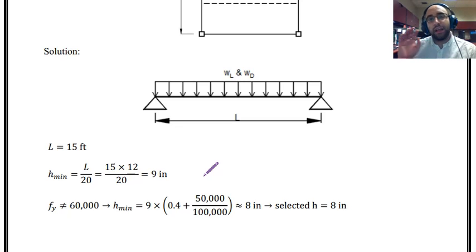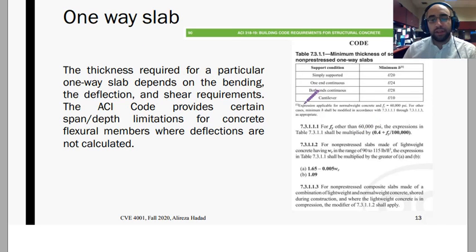Once you design this and you design the slab in the project, you will become more and more familiar with the slab design, and then based on that you can see that we are not really worried about the design of slabs, because just providing the minimum height and the minimum reinforcement will give us enough strength to carry regular loads. So minimum height is 9 inches, but the important thing over here when we are using this table is